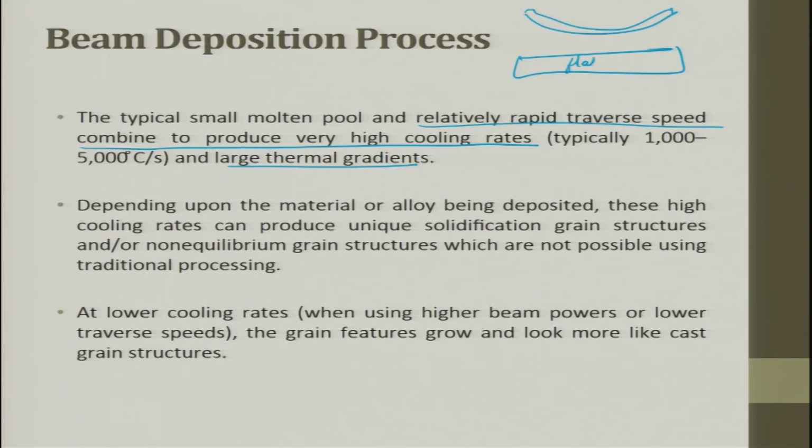This is flat and this is warped. So, large thermal gradients should be avoided. For this, what we do is we try to do the entire exercise or the product development in an ambience where the temperature is maintained at a certain level, so that the thermal gradient is avoided.